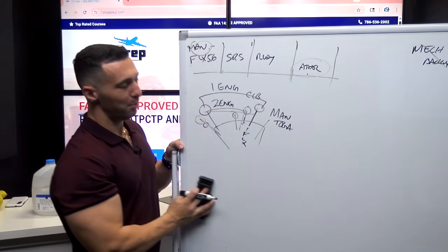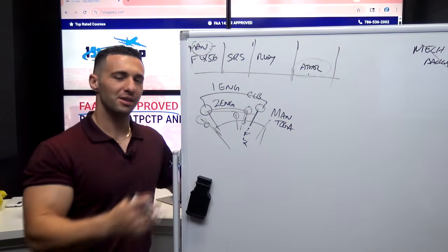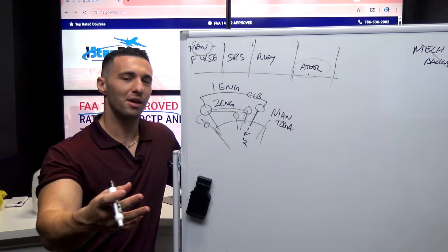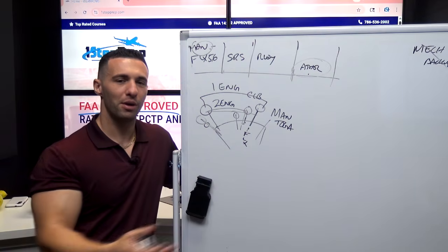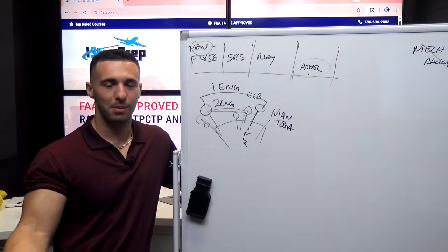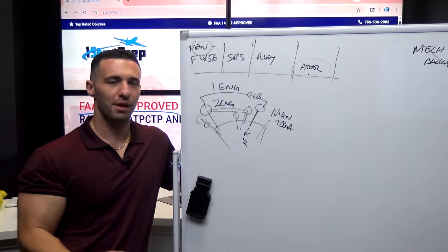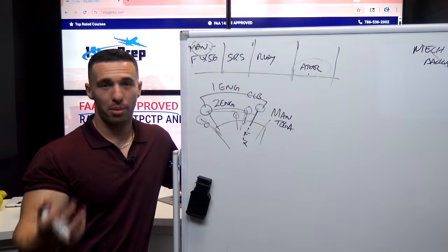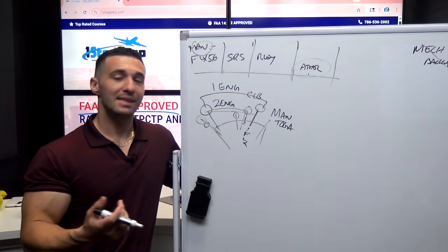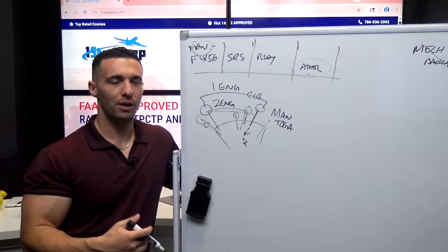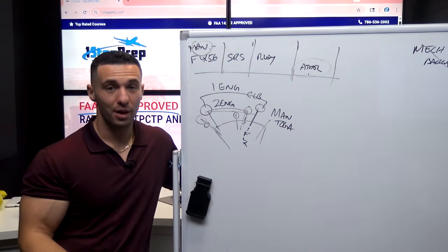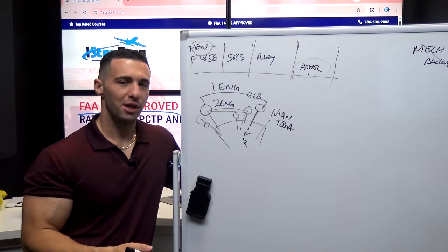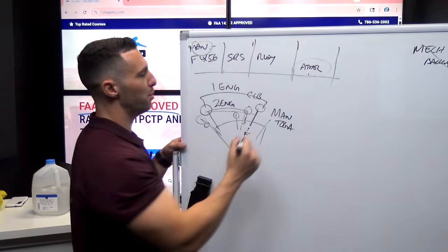And the channel that's being used is directly tied to the autopilot that's engaged, right? So if autopilot 1 is on, then FMGC 1 is powering auto thrust, and if autopilot 2 is commanding, then auto thrust is slave to FMGC number 2. And if no autopilot is on at all, then technically it defaults to FMGC number 1. But it is very much a dual channel system, just a single auto thrust push button.